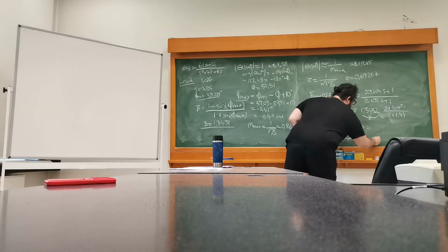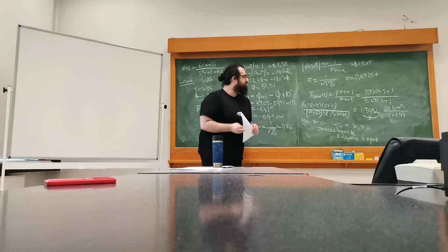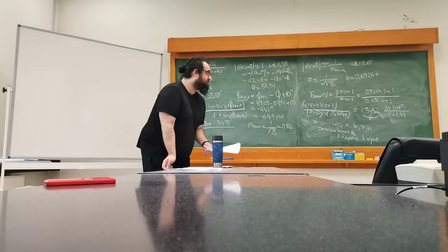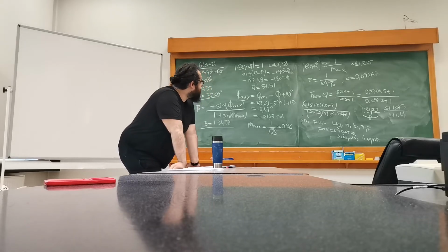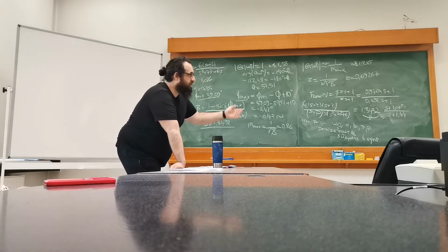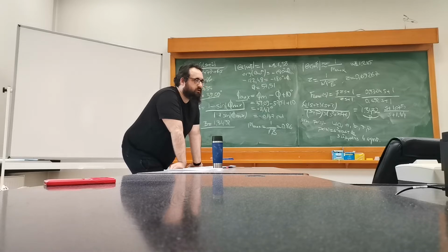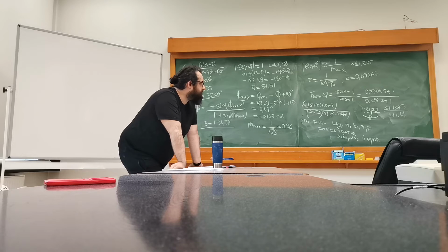So therefore, we have four equations. Therefore, we have to parameterize that. Maybe choose z, maybe choose p, and then try to design one. If it's not really required to be optimal, I might go ahead and choose omega n in order to come up with just a working solution. But again, a and b should be positive values in order to have stability, etc. So this part is a bit harder to do in the time domain because there's an optimization problem waiting for us.